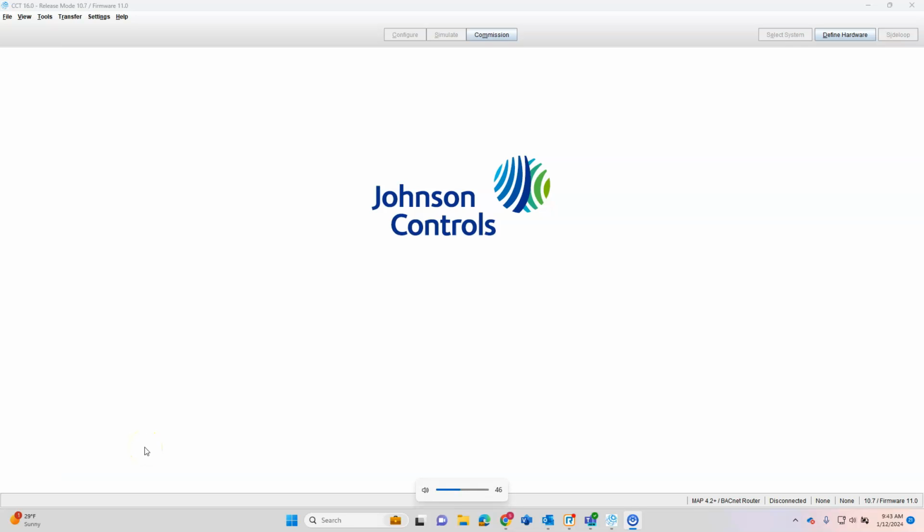Hey, today let's talk about doing a pressure dependent VAV system from scratch in Johnson Controls. I know last week we did a complete VVT system with a unitary controller that controlled a few zones. But what if you just want to use the VAV controller as a pressure dependent device on a network somewhere, or even not on a network? I'll show you how to do this from scratch.